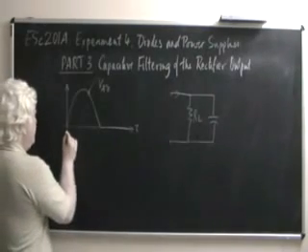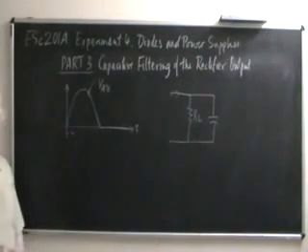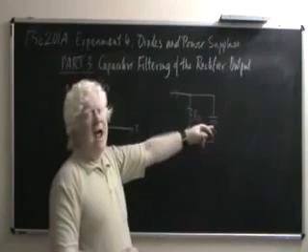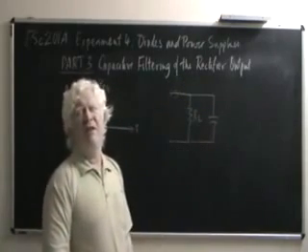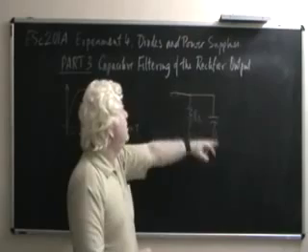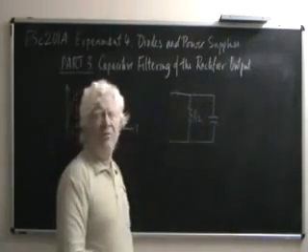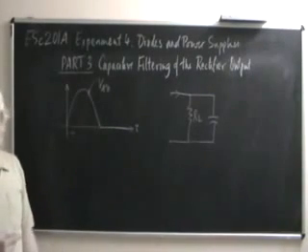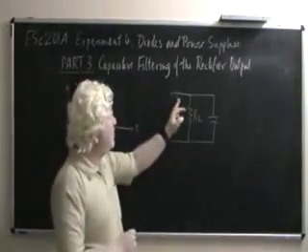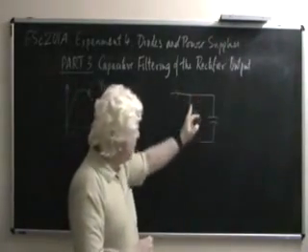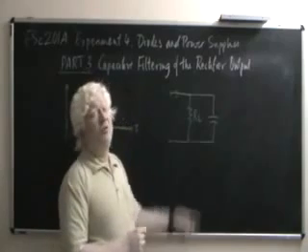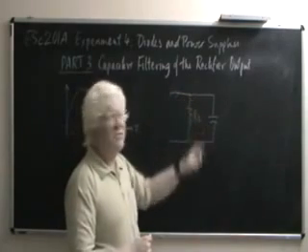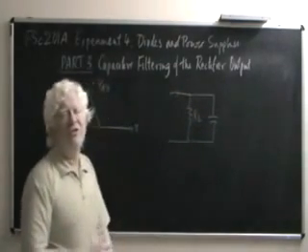Then, as time proceeds beyond this point, a positive voltage is applied to the uncharged capacitor, and with a very small time constant, because there is literally no resistance in series, the capacitor voltage will follow the supply voltage. Simultaneously, the rectifier output is also forcing a current into the resistor. But while passing current through the resistor, the same voltage also charges the capacitor almost instantaneously.